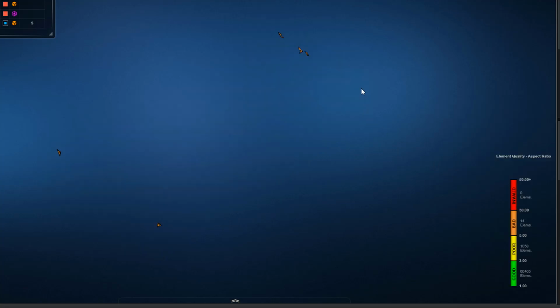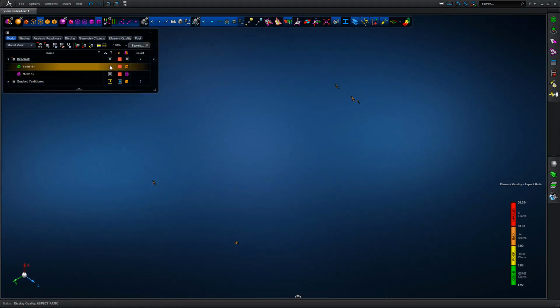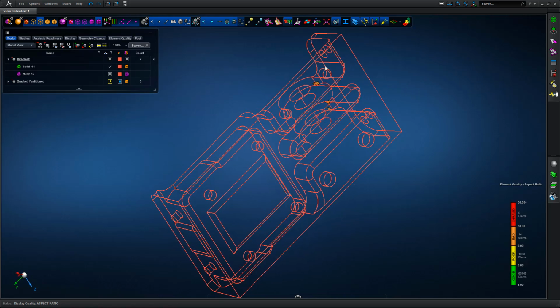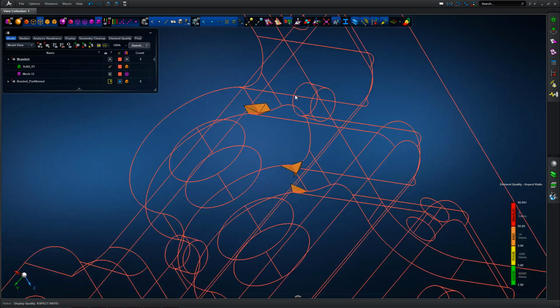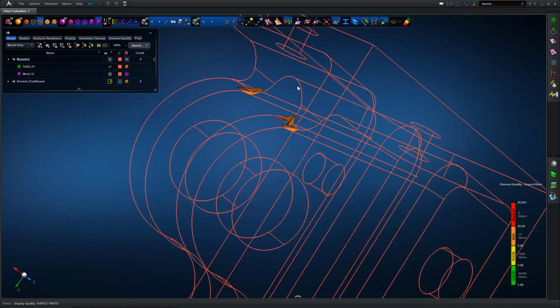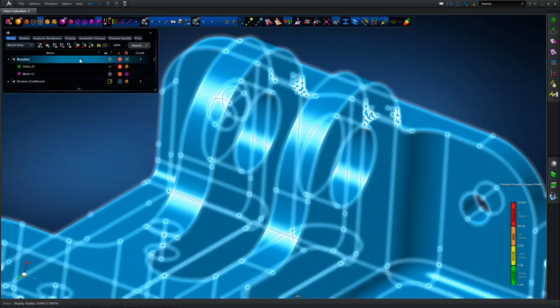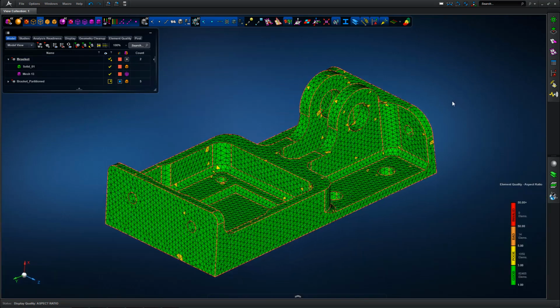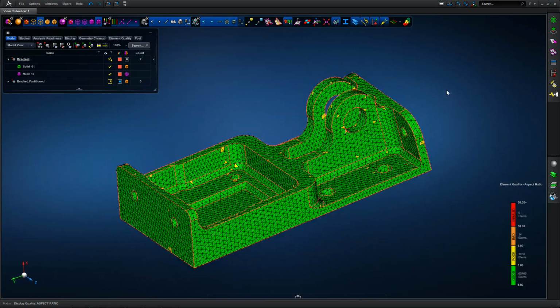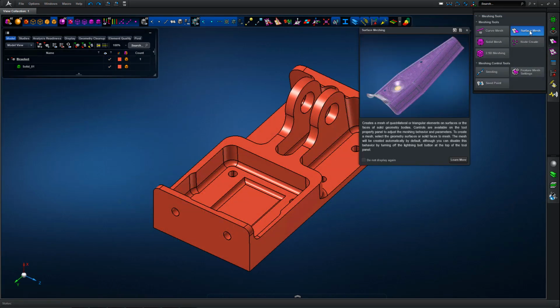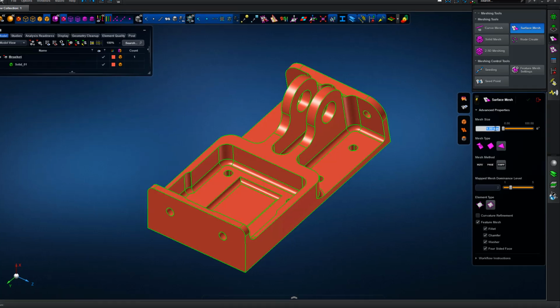We've got some bad elements, so we can show only those bad element regions along with the underlying 3D CAD definition, and we can see in this region we've got manifold edges coming together for two different fillets and one of the surface edges. So maybe the 2.5mm edge length is not appropriate in that region if it was a region of interest, but certainly we don't have any invalid elements.